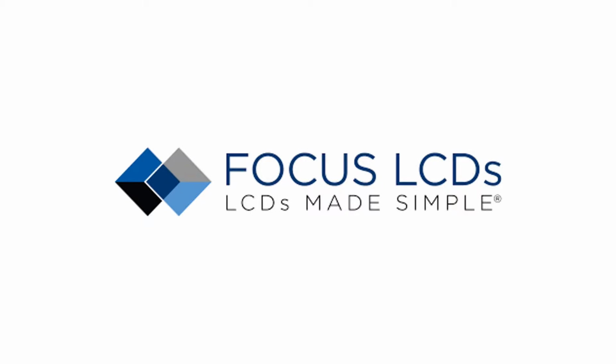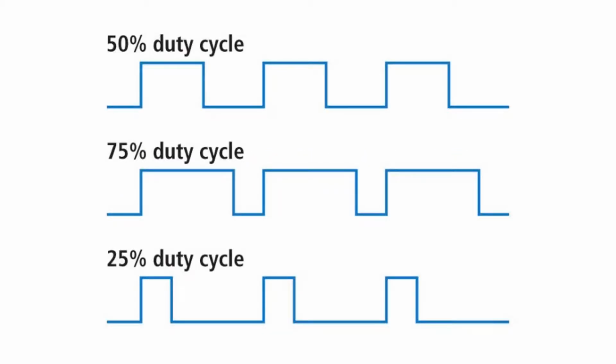of the LCD backlight. On the screen you'll see different examples of duty cycle, which brings us to the concept of duty cycle. Duty cycle is a percentage of time on divided by the total period of time. The total period is a combination of time on plus time off. Now this is where it gets fun. This period is the inverse of the frequency of the waveform. If this signal spends half of the time on and the other half of the time off, then the duty cycle is 50%. Let's say the duty cycle is 75%. That means the backlight or device is on for 7.5 seconds for every 10 seconds.